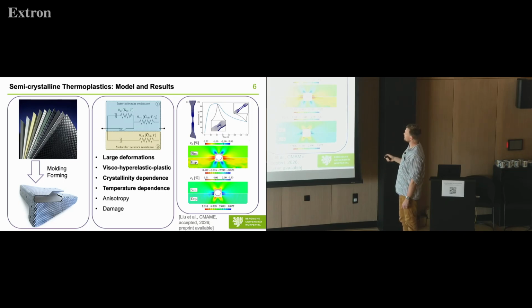And this is really stable and working nicely. In order to compare this with experiments, from exactly this example, we used some DIC measurements, which a former colleague of mine did, to compare the local strain patterns in horizontal and vertical direction, which seem to match up quite nicely qualitatively.